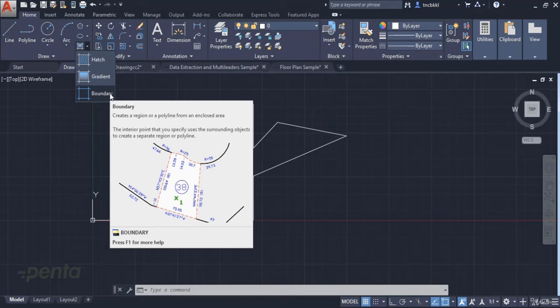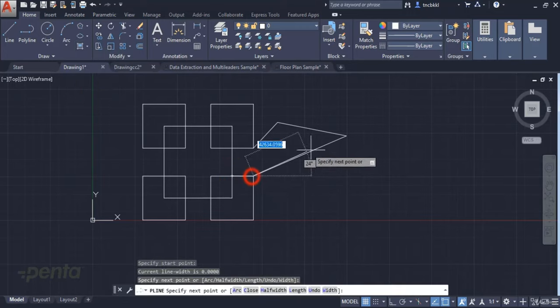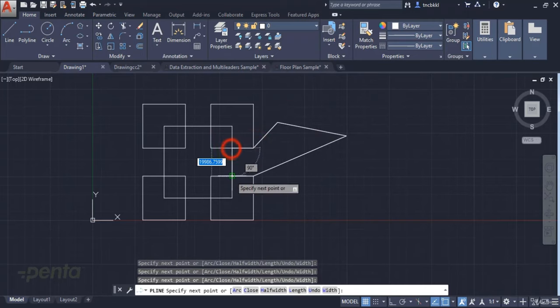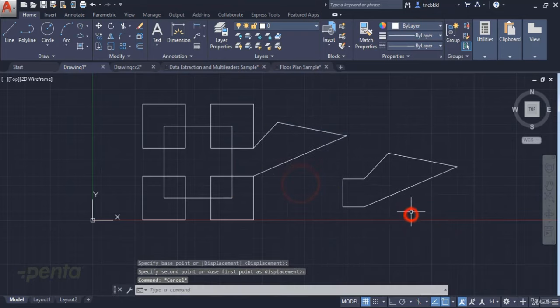When we want to calculate an area, sometimes it asks us for an object. And it might be easy to show a square, but to show the inside of an object as an enclosed space, we sometimes need to draw it with a polyline. Like this, we can divide this area like this. We can create this area here and later carry this object outside. When we want to do something like this, we can use this method.